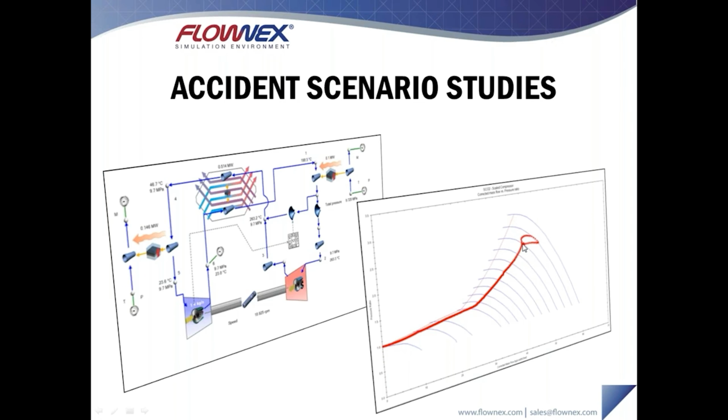So it originally started up here on the third line from the top. It then shoots to the right as soon as the generator is decoupled because the turbine train increases in speed very rapidly. It then loops around and gradually begins to taper down towards its zero mass flow rate condition. The control of this is done through the two valves, as I mentioned.